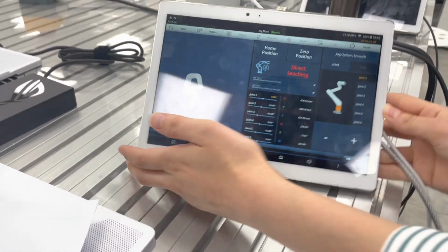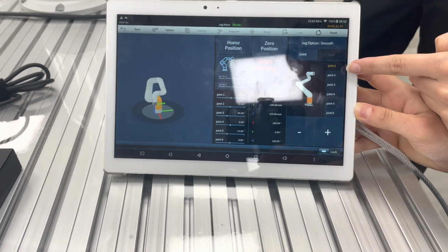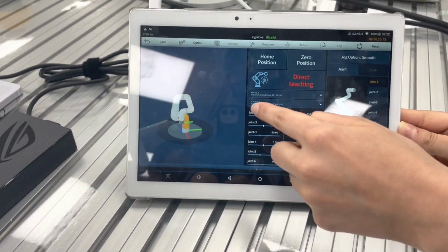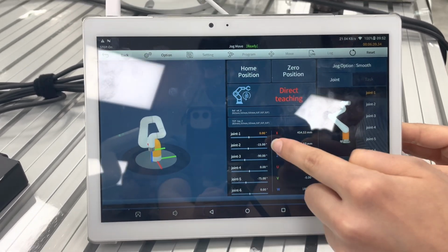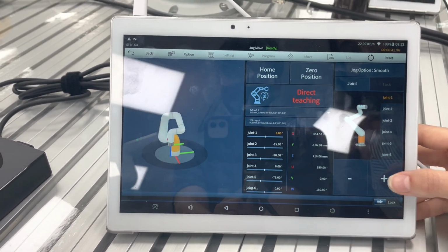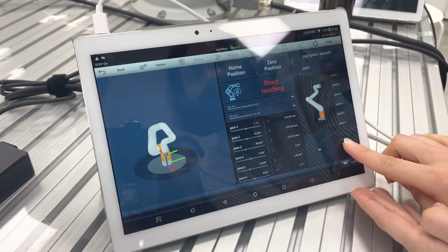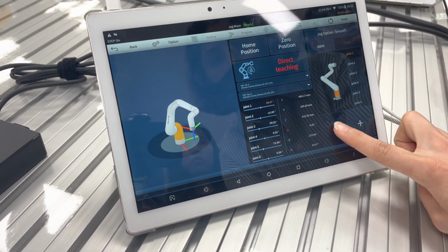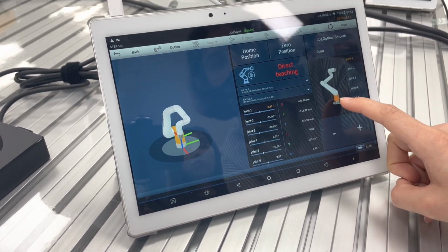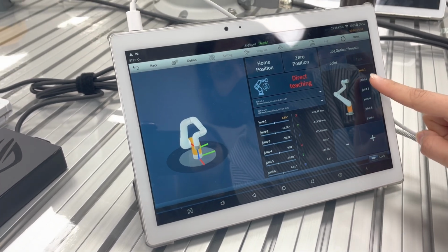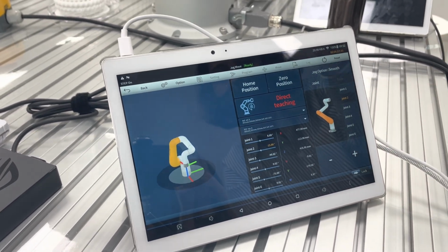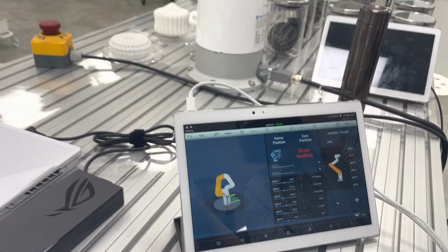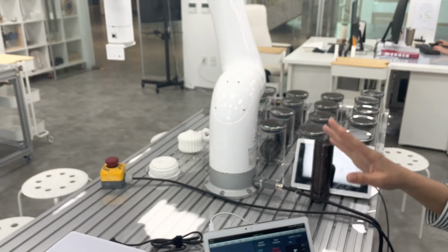Example here, I have selected this joint 1, okay? And now I want to move it. And you better also look at this part because while I'm moving it, it will also change here, the angle. To see, it's also changing and you can also see the simulation here. And you will see that the joint 1 is selected here. Then joint 2. When you're working with joint 2, you should be very careful because it has the most potential to be like to hit you or like hit anything on the desk.